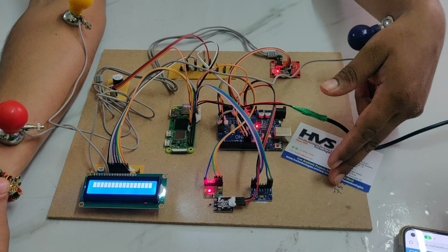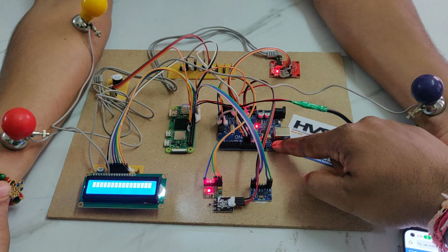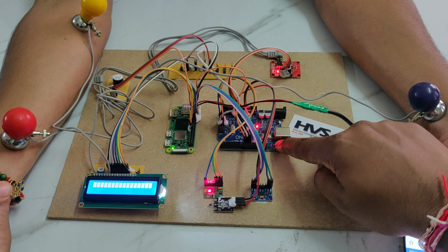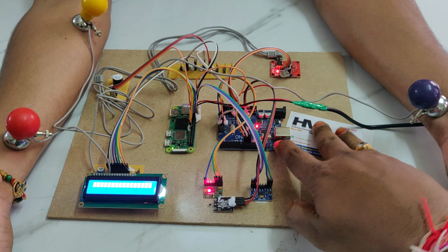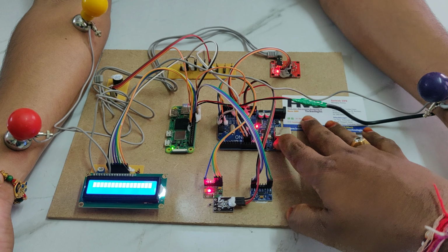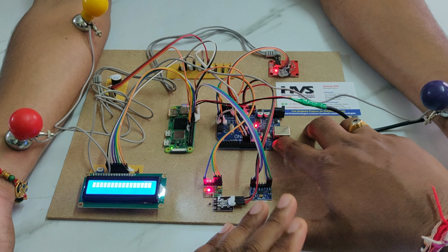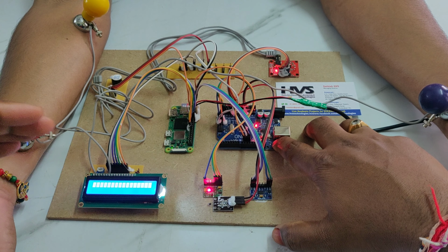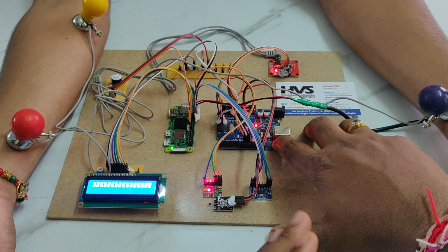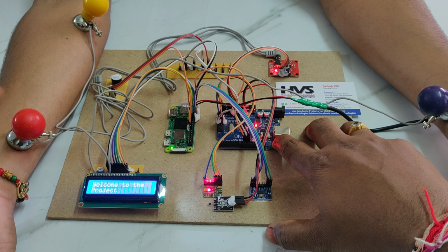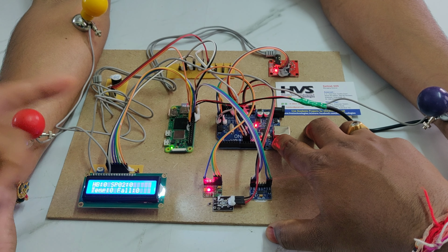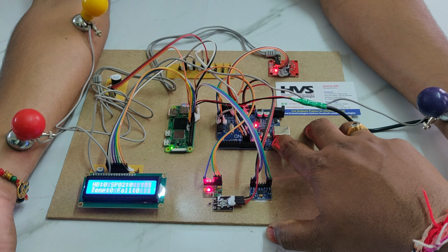Once the power supply is on, hold this reset switch. This is very important. This is the reset switch of the Arduino. Hold the reset switch till a welcome message is displayed on the LCD and the buzzer turns on and off two times. It means we need to hold the Arduino to send the data. There is a process delay. If we send the data continuously, initially it will take around 20 to 30 seconds to log into the operating system inside our memory card.